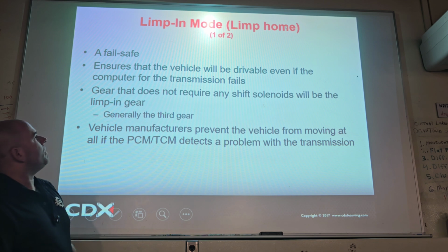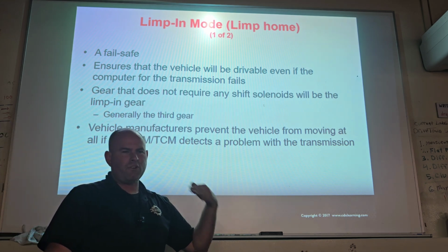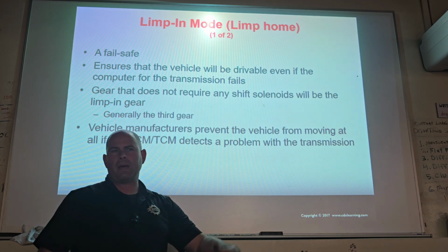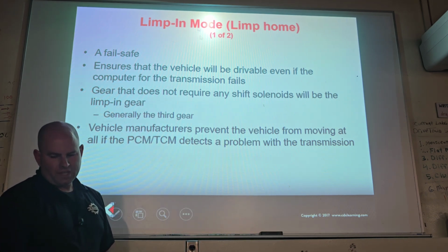And then similar, you may call it limp in or limp home. That's what we were talking about. If there's a fault, it may command 4th gear max line pressure. That would be kind of the default. Cool, and that's pretty typical.